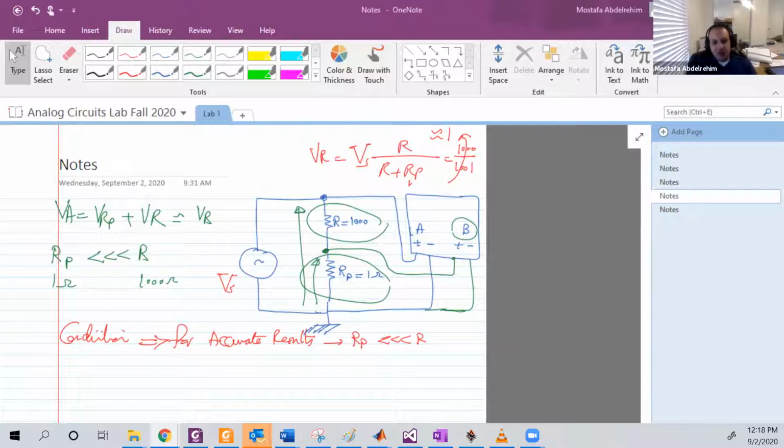The channel B connection will be the same, but I'm gonna connect channel A to the same ground as channel B, which is 1. Now channel A is measuring from this point to this point, all that voltage, just like what I showed in the one node.